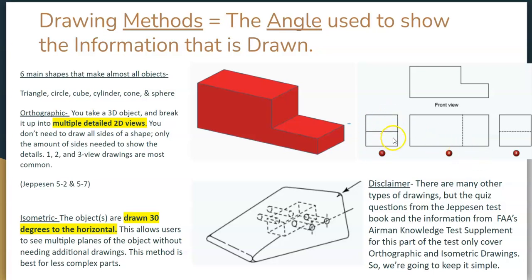And then you have your two side views over here. This will be your left view. I think that would actually be your right view, and then this would be your left view over here. Because again, if you look at it from the right side, you'll see that there are two ridges right here. There are two faces right here. But if you look at it from this side, which is option number 3, you're not going to see that there's a ridge right here, so the hidden line is used to show that.